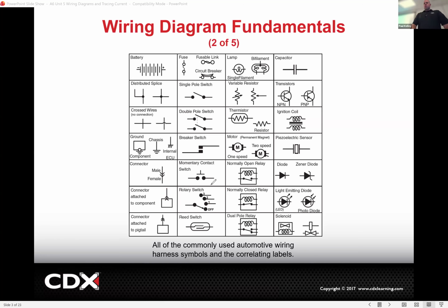Whereas if you trace it with it in the off position, that's only going to tell you what should have power if it's turned off. And if your problem's occurring when it's in the speed 2 position, you might as well draw it as if it's in the speed 2, trace it, and then do the test while it's in speed 2. Does that make sense?